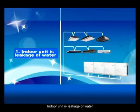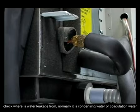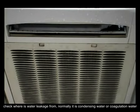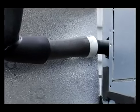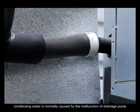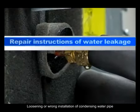Indoor unit water leakage. Check where the water leakage is from, normally whether it is condensing water or coagulation water. Condensate water normally deposits at the indoor air outlet and panel. Condensing water is normally caused by the malfunction of the drainage pump, or loosening or wrong installation of the condensing water pipe.